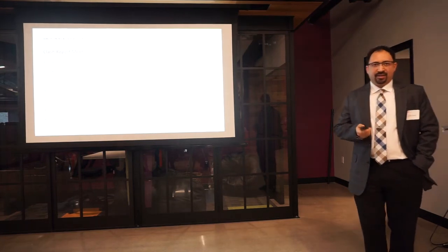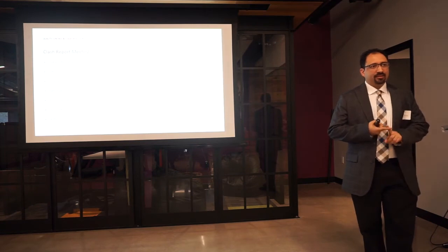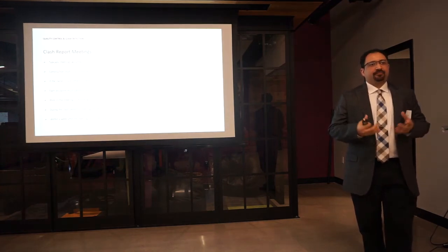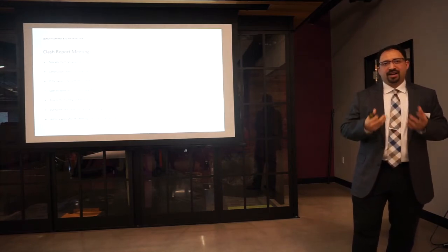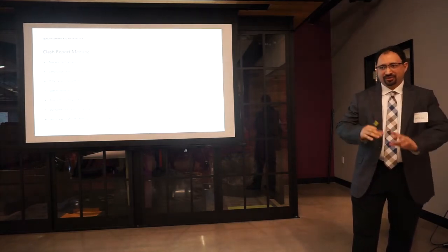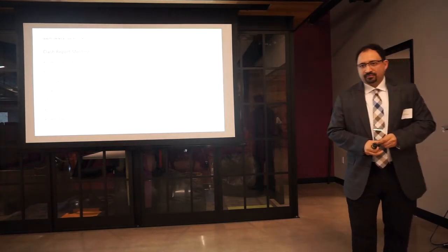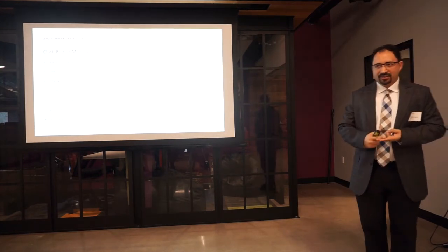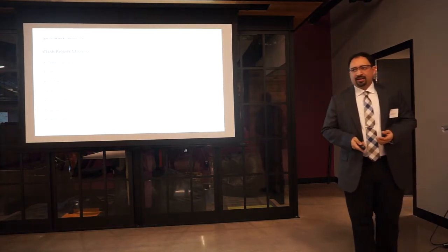We would have a meeting every Monday morning with our MEP team. We had the MEP team generate their own reports as well, which they resolve a lot of the clashes on the spot, while other things were found to be a little bit more intensive. They would have to resolve those clashes later on their own drafting. However, in these meetings, we established the timeline, what we intended to discuss every meeting, and we established that in the BIM execution plan as just our set standard.